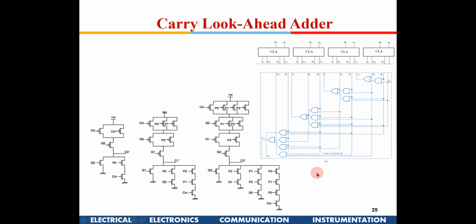Now if you see here, when we were talking about the gate delays, I said this is 1 gate delay, this is 2 gate delays, I am computing like that. But you might want to tell, sir, this AND is actually a NAND followed by an inverter, this OR is actually a NOR followed by an inverter, because in CMOS you can't make an OR gate. So actually this is 2 gate delays, and hence from here to here it should be 4 gate delays. But that is not actually the case.